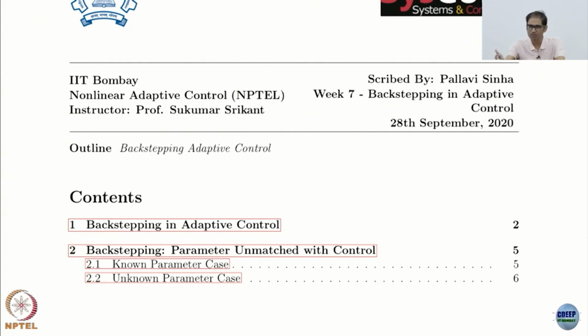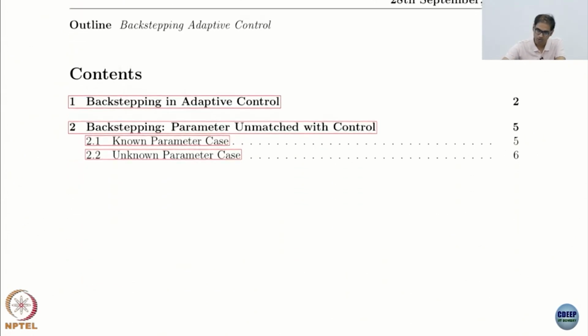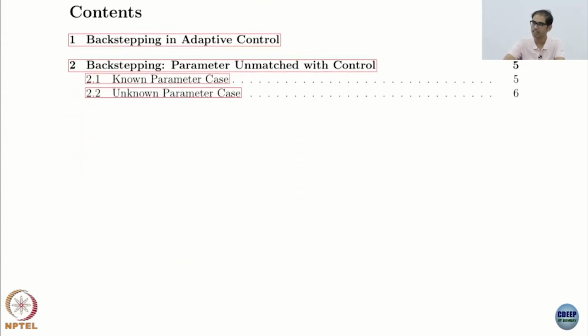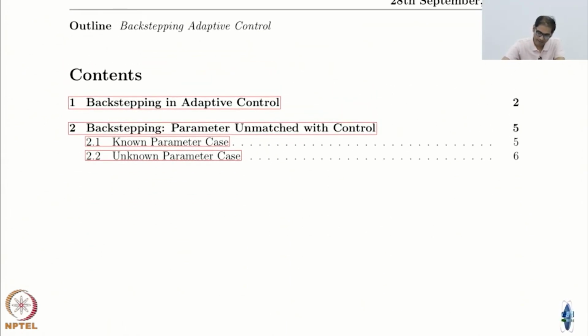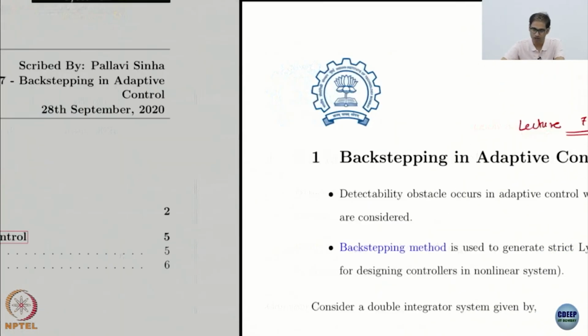He is one of the key researchers in the area of adaptive control. So the entire concept and utility of backstepping came from adaptive control, not the other way around, although it seems like we are doing the other way around. We already did backstepping ideas for the nonlinear system case, very powerful. You can easily construct CLFs sequentially and do a lot of things. In fact, you can even automate it, symbolically generating new functions if you don't want to keep track of the complicated terms. Backstepping came from adaptive control, so obviously it is very applicable in adaptive control. Modern adaptive control uses a lot of backstepping.